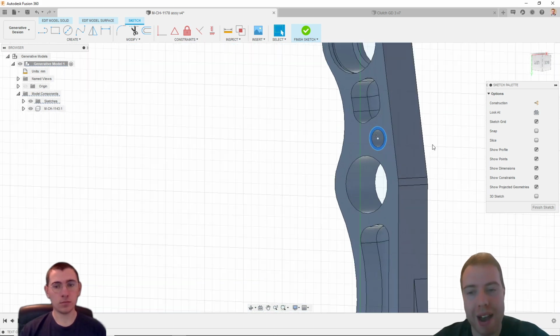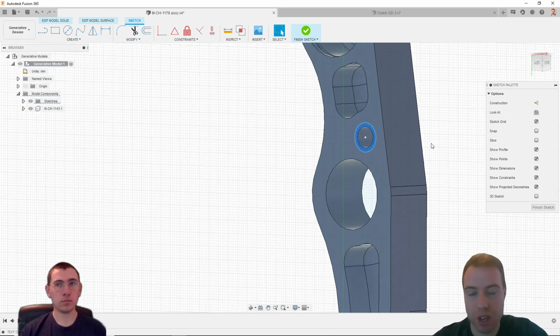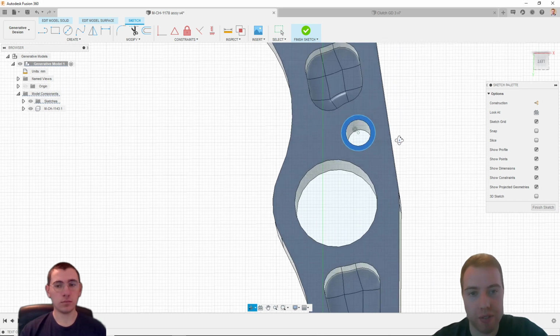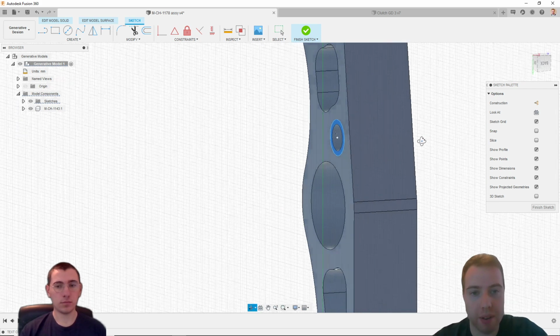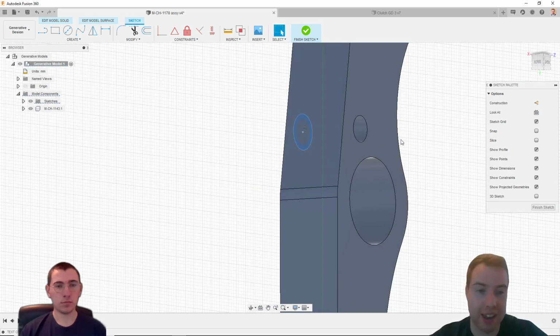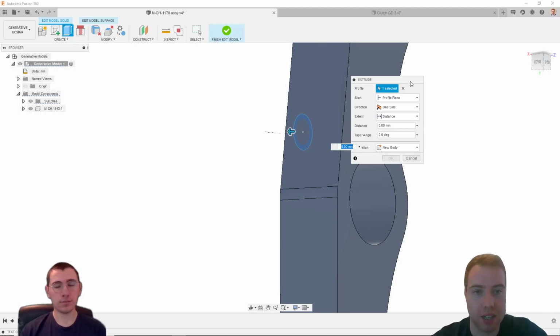The amount of geometry that you need for your preserved geometry is a bit arbitrary, but essentially the less information we give generative design, the more freedom it has to be creative and come up with its own solutions. So in general, if we create less geometry for our preserve, we're going to give generative design more freedom to design things.